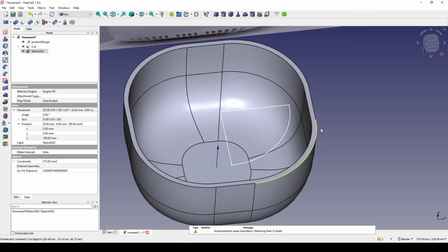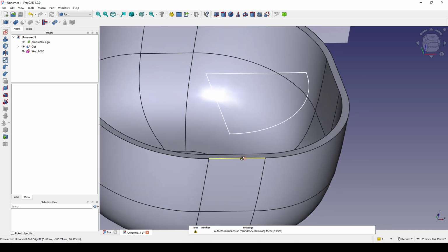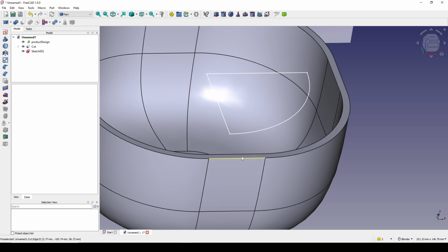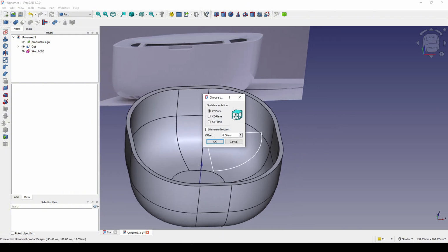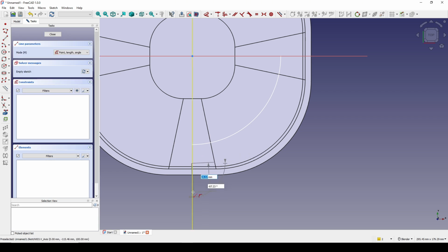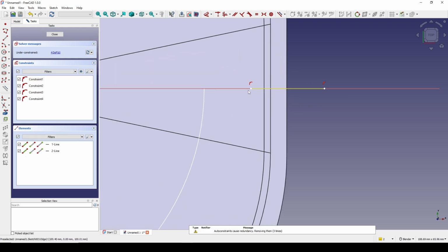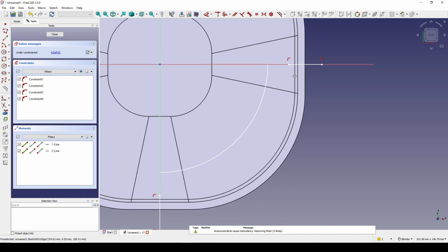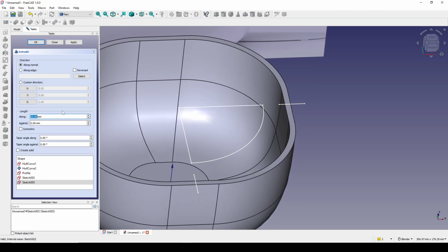Alright, now I close. Next, I want to create another sketch in here, and extrude and create a slice to generate a small line in here. I create another sketch on the top view and also offset this one to 100. And I will create one line in here and another line in here, so that these two lines just overlap with this surface. Then I close. I will extrude this sketch to 20 and symmetric.